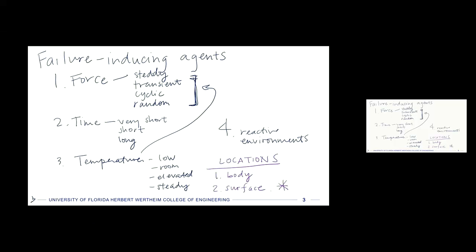and this is actually the much more common one. And so if you think back to courses you've taken where you looked at a beam, right? A cylindrical bar, maybe it's an axle, maybe it's rotating, and if it has different dimensions on it, then where it changes dimension, those are the stress concentration points. So any bending moments or other loads on that shaft are going to cause failures first if the loads continue to increase at those locations which are on the surface.